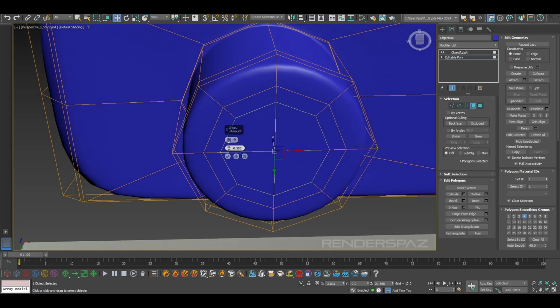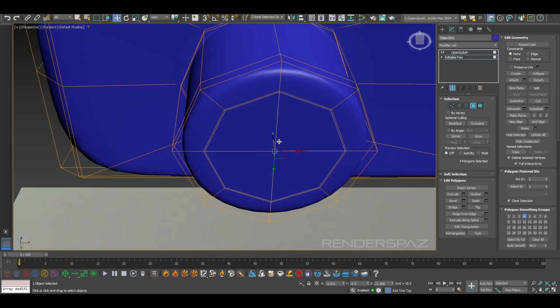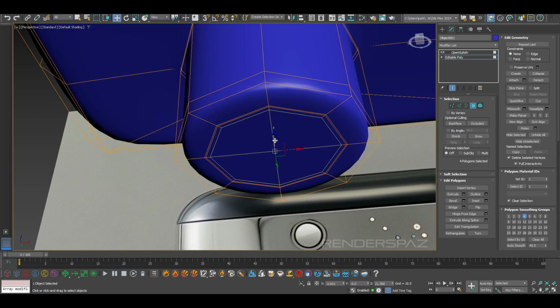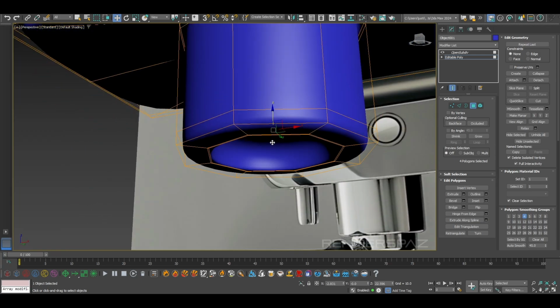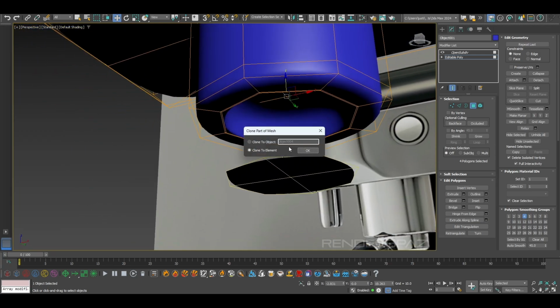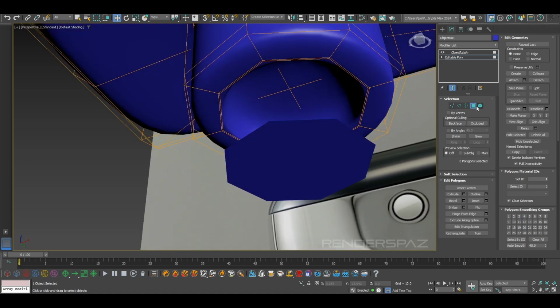Let's do an inset before we do that. This way I'll get a nice little edge. And then dragging it up. Don't hold shift at this point, sorry. You just have to add that extra edge and just pull up, and that should give us the right extrude here.